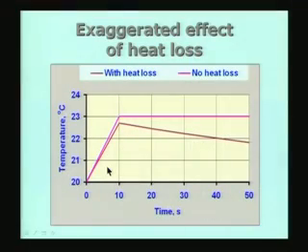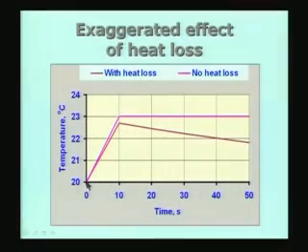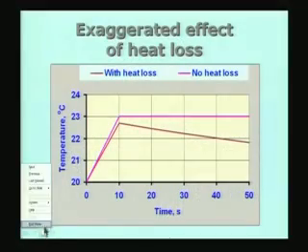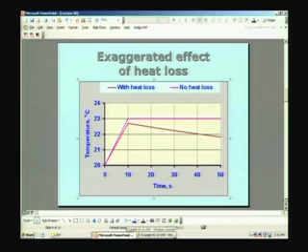Now, before we do that, let us also look at the expression we had. We had an integral of T minus T1 dt. If you remember, there was K multiplied by the integral from 0 to t of (T minus T1) dt, and that can be obtained as the area under the curve during the mixing process. This is the curve, actually it is almost a straight line. So, half of the base times the altitude gives the area under this curve, and that is going to give me the integral part. The K part is going to come from the cooling curve. So, let us go back to the board and look at this in more detail.